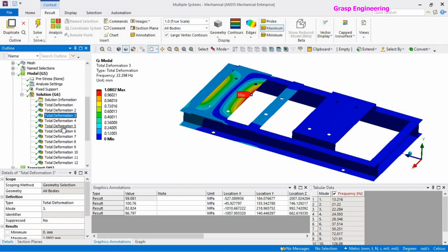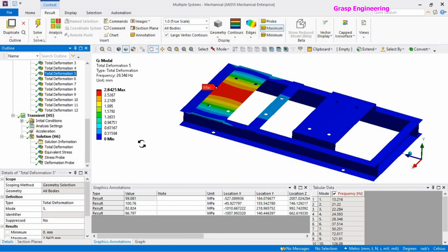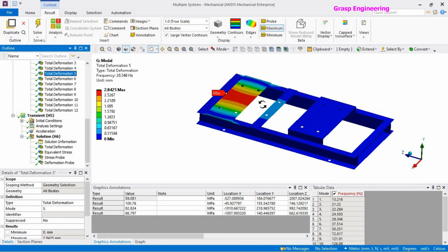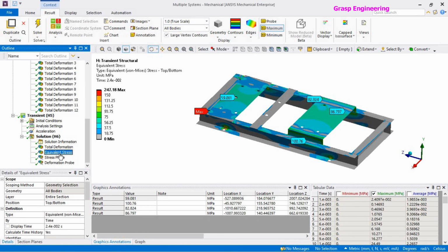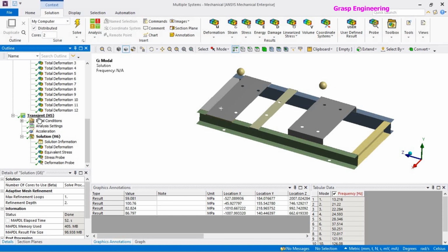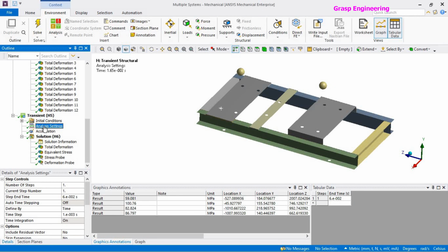Okay, and mode shape, mass participation factor, and then stress. Once you strengthen your part, your mode shape will change, like your vibration will change in the directions. So accordingly you need to check the stress also. Stress will shift. So that is the importance of modal simulation, and then you can get the results similarly on the responses which you got from the natural frequency. On those responses you are applying the shock profile.